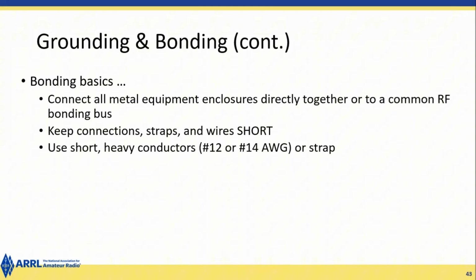If a ground connection is resonant at an odd number of quarter wavelengths, it will generate high impedance, which enables RF voltages on enclosures and cables on those devices. So try to avoid wavelengths of what you're trying to operate on for lengths of cables.